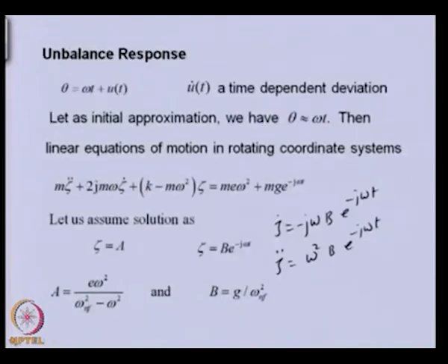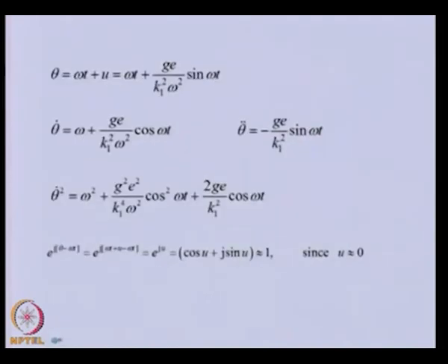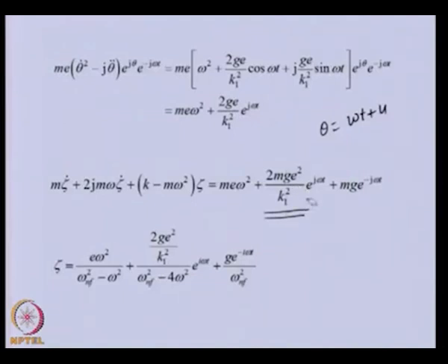If we go back to the equation of motion which we linearized by putting theta is equal to omega t, we had these two terms. Now, with this variation, we are getting an additional third term, and you can see it contains the gravity terms also, apart from the other parameters, but this is the main parameter. Now we want to solve this particular equation. Because this equation is linear again, we can solve for this and this force separately and add them. We already solved for this and this in the previous expression. Now we will solve for this, and we will see that the solution for all three will be like this. Basically this is the additional term which we are getting, which was not there in the previous solution.